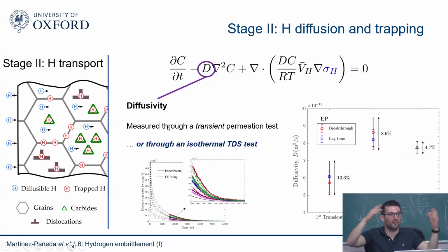Because if I think of a pipeline, for example, and assume this is pure iron, representative of those pipeline steels, whether I'm here or here, this means that the steady state of hydrogen concentration in a pipeline will be achieved in 2 days or 2 days and 10 hours. So for an engineer, that's not a very big deal. For other things, it might matter more.